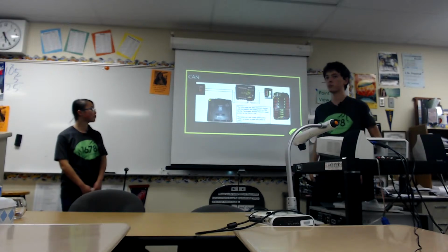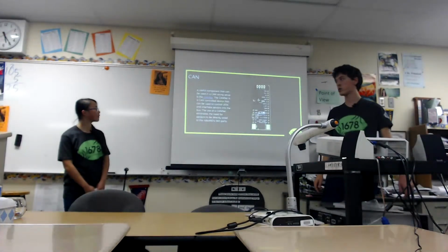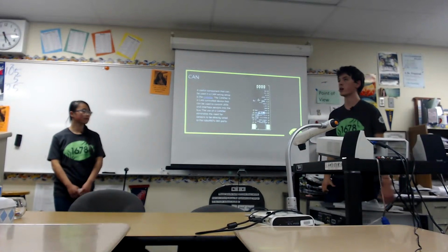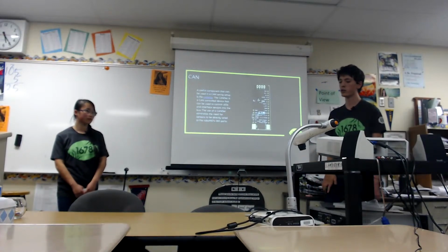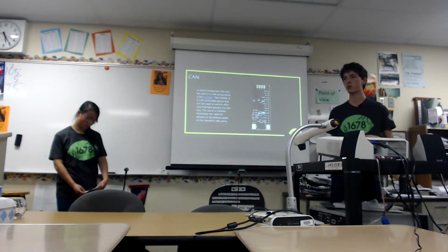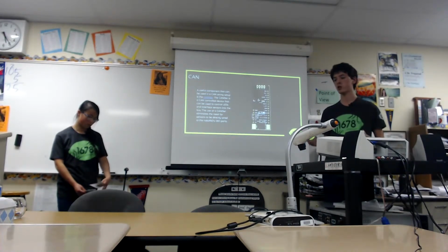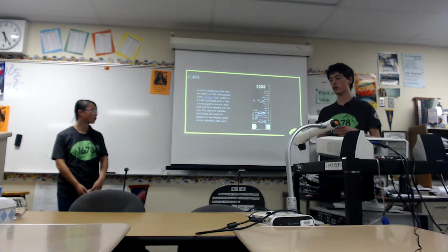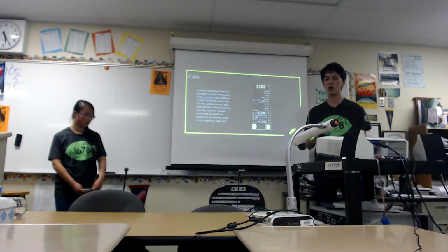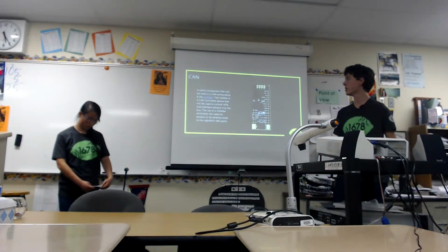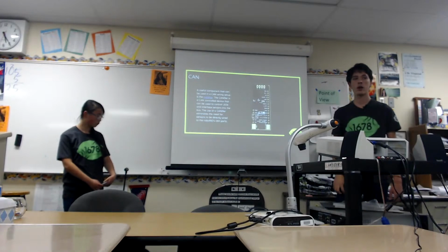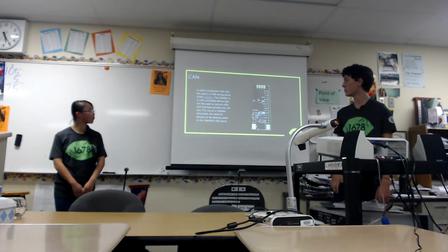It doesn't matter where. All right, and so this is the CANifier. It's a really useful CAN component, because you can convert digital input/output sensors to CAN. It allows you to use sensors in the CAN loop without having to run a cable all the way back down to your RoboRIO if it's really far away. Instead, you can just run a short little cable to your CANifier and then convert that to the CAN loop. It also helps with wiring.